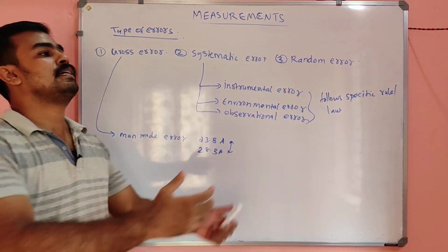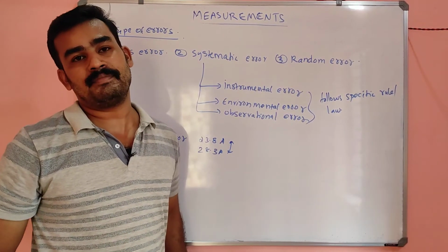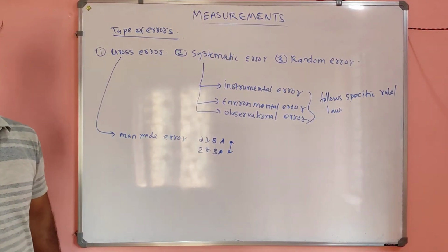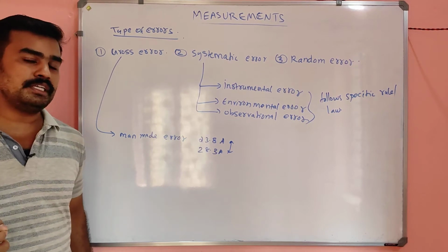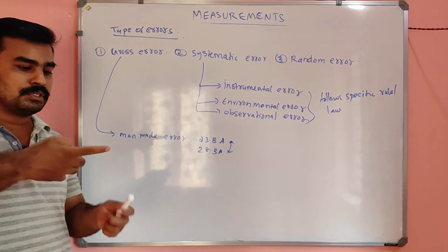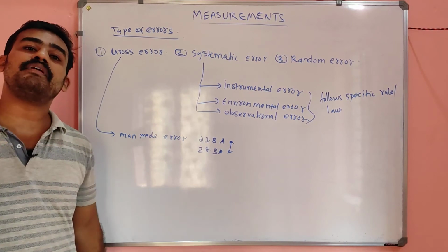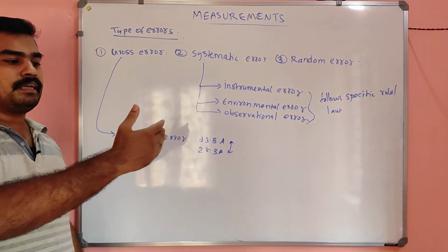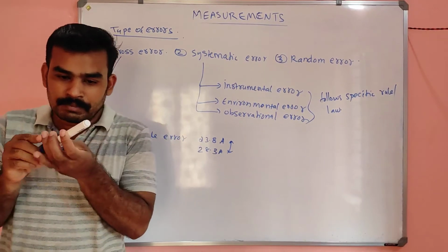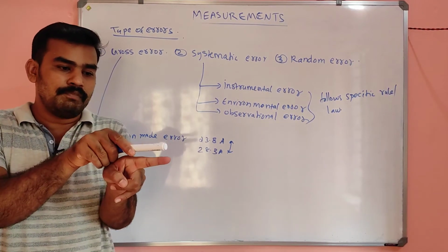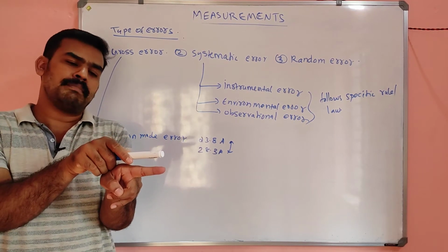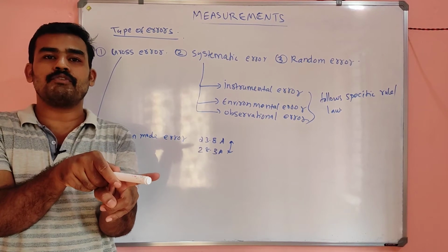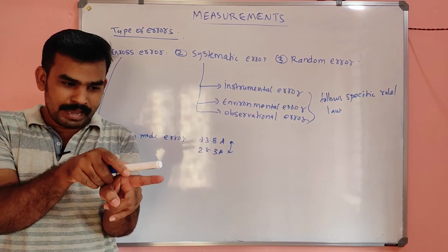Suppose we bought a new instrument and didn't set the zero. Normally in the laboratory, the first step of every experiment is to set the zero of the voltmeter, ammeter and wattmeter. Before taking a reading, the pointer should be exactly at zero. But due to some reason, it may be away from zero in the forward direction, so we have to bring it back to zero.